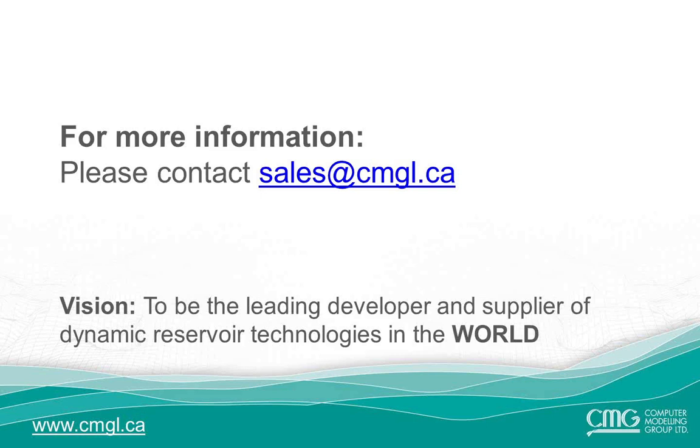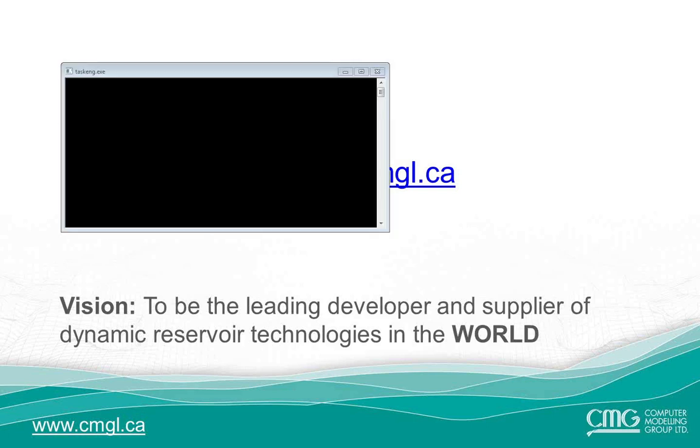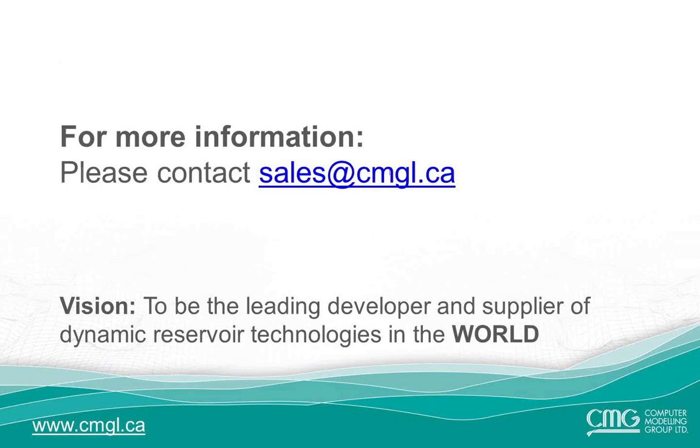The next question is from Arun Kargoria. He wants to know, can we use this process with STARS? So this can be used with STARS. Currently, I think the wizard is only available when looking at IMEX and GEM models. However, all the capabilities have been added to each of the 3 simulators. So you can start off with an IMEX model and then copy the fracture properties from that IMEX model into a STARS model. So this can allow you to do things such as thermal calculations in the fractures.